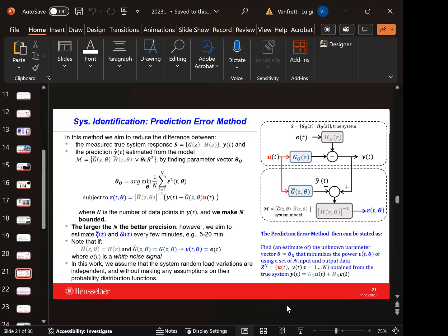But basically, if the random loads are observable at the point where you measure, and if your excitation and the measurement points are not too far away, then the dynamics will be the same in the excitation model and in the random load models, because there are two excitations: one is unknown and the other is what you excite. So effectively, it's true.